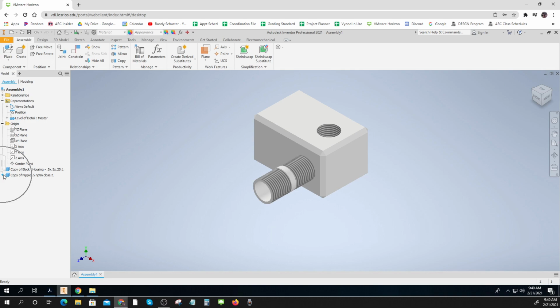And so then if I come to my little plus over here and I double click the cylindrical, it lets me edit that relationship. In the linear, I need it to go backwards in. See, plus is coming outwards. That's that little arrow right there. And I think I recall that these were like 0.28, so I'll go minus 0.25. If I were really taking care, I'd go back and look at my formula to find out what standard engagement is. But that's good enough for what I've got right now. So there I go. I've got those two.